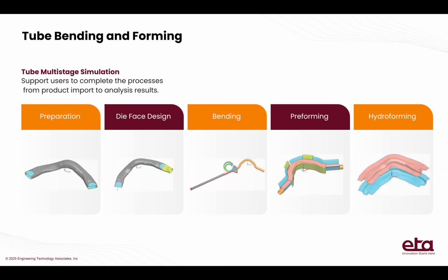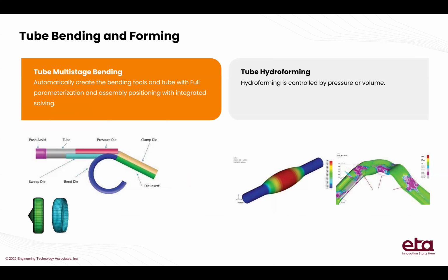So this tool will push the tube and make it ready for the hydroforming. Of course, at the last, you have the hydroforming, so it will hydroform the part to the final geometry. Okay, so this module automates center line creation, bending station, tooling station, and hydroforming setup for tubes. It supports multi-stage operation and variable pressure curves.